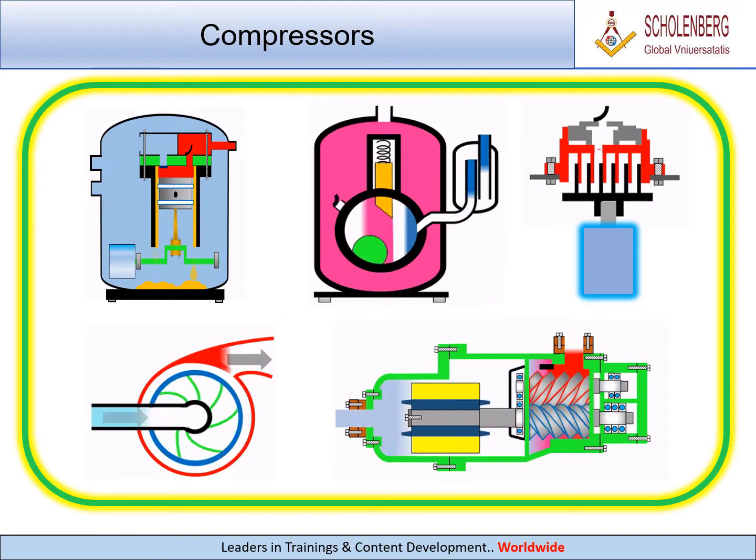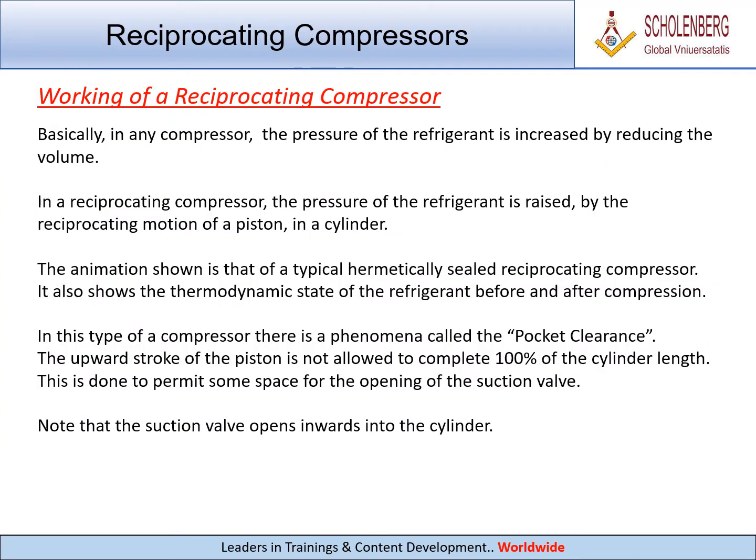Compressors. Working of a reciprocating compressor. Basically, in any compressor, the pressure of the refrigerant is increased by reducing the volume. In a reciprocating compressor, the pressure of the refrigerant is raised by the reciprocating motion of a piston in a cylinder. The animation shown is that of a typical hermetically sealed reciprocating compressor. It also shows the thermodynamic state of the refrigerant before and after compression.